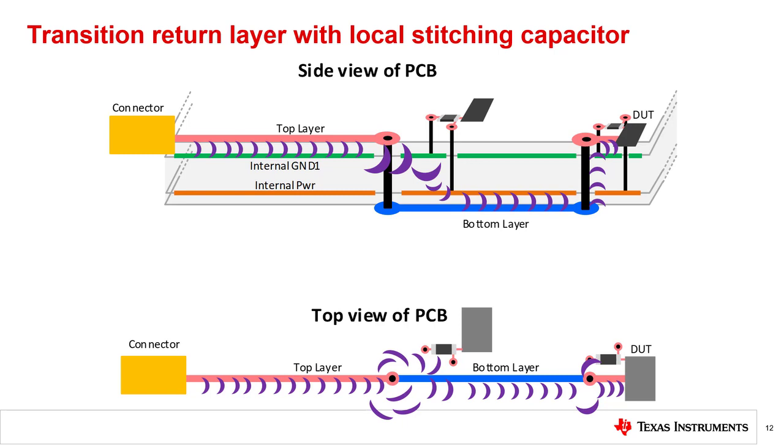One problem here is that you cannot have a stitching via from power to ground as you would short the power to ground. Instead, the return current must transition through a stitching capacitor. In many cases, the stitching capacitor will simply be a decoupling capacitor closest to the via transitioning layers. In this case, you can see that the signal transitions from the top layer to the bottom layer with minimal RF emissions.